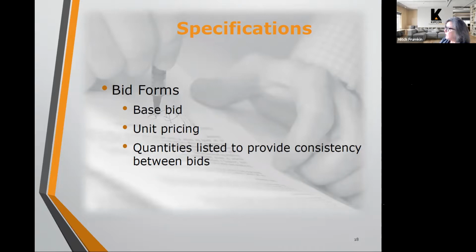It may include excavating and backfill of unsuitable material. It may include that geotextile fabric that I mentioned, and crack repair fabric. It may include various types of repairs to catch basins. So again, base bid is what you know needs to be done. The unit pricing we request for typical items that come up as surprises during pavement projects.